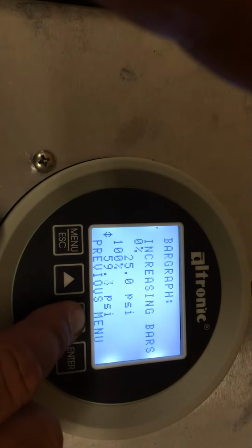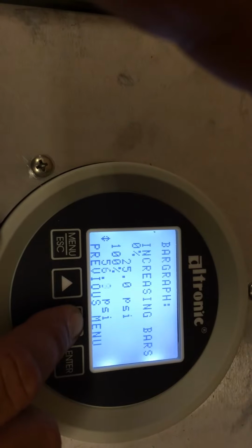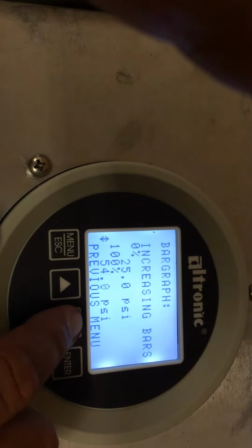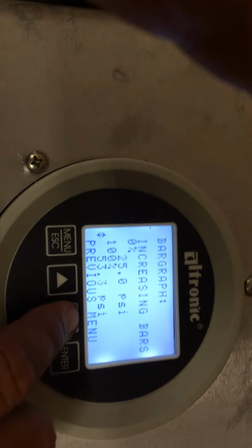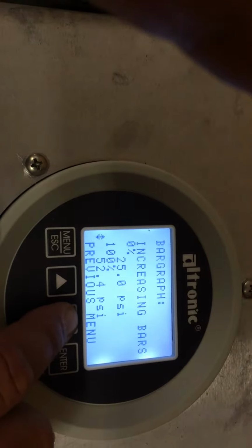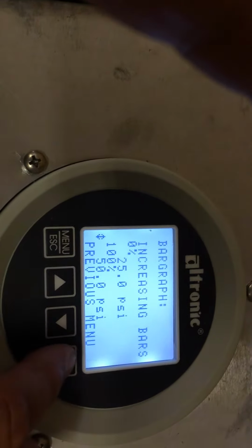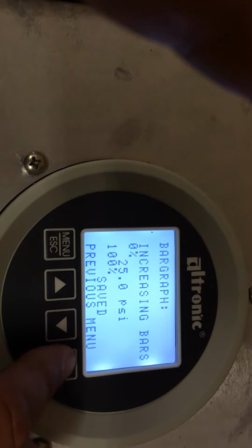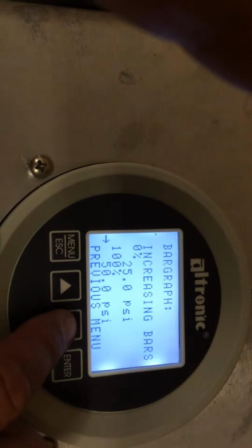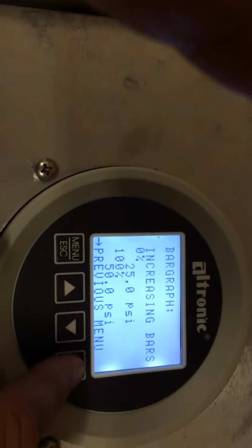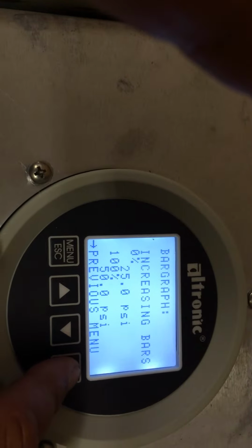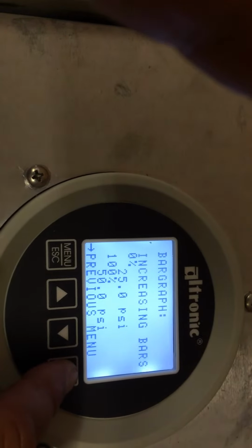The idea is to get them to where you're operating. Let's say in this application they could go as high as 70 or 75 pounds, but from 50 pounds to 75, they're going to be running wide open. Same thing, 25 pounds down to maybe 20 pounds, they're going to be running dead slow. All right, so I've got 25 for the low, 50 for the high.